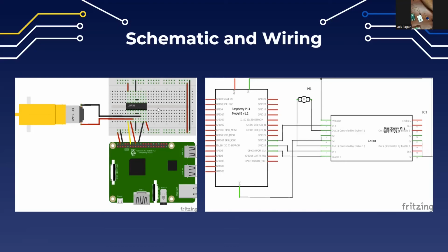So let's reference the schematic here, or drawing. So you see, I connect to the lanes like I would normally to apply power. What I've done here is I have 2 wires connecting both sides because they are not connected to each other. This will make sure that both sides have ground and VCC power going to them, so that if I have to connect something on the other side, I can just wire it up pretty close rather than bringing a wire across the board, which you don't want to do.